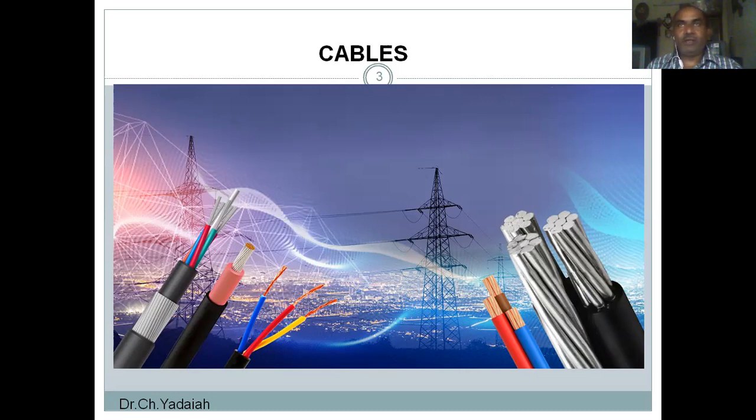We already know that cables or conductors mainly depend upon the load, the loading of the motor or machine. If the loading of the machine is more, we require a larger diameter of conductor, whether it is aluminum or copper.